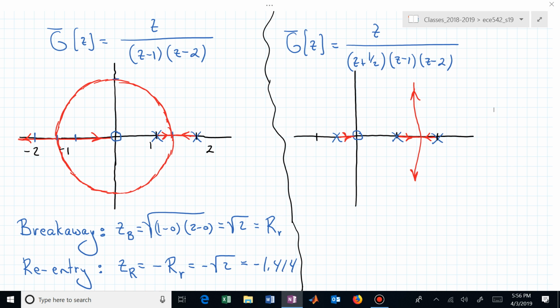Finally, I go all the way to the left of all of my poles and zeros. Let's say I'm at minus 7, and I look to my right and I say, oh, I have 3 poles and zeros. That's an odd number. All of that from the origin to minus infinity belongs to the root locus. What happens off the root locus we'll figure out a little bit later, but in fact, this is the 2 poles and a 0 walk into a restaurant joke, right?